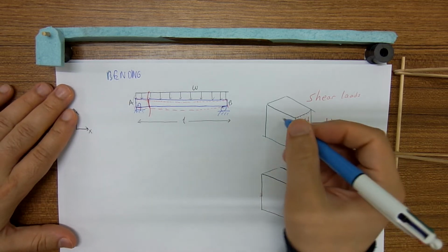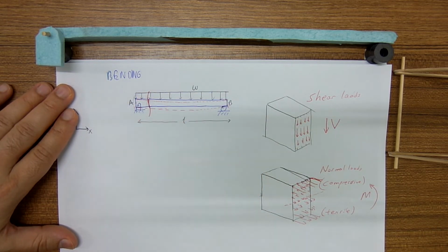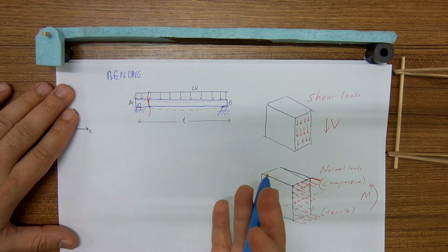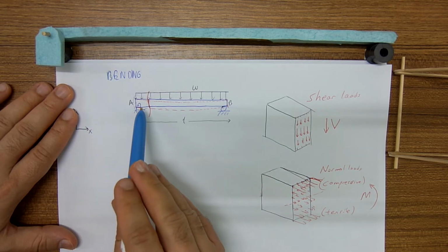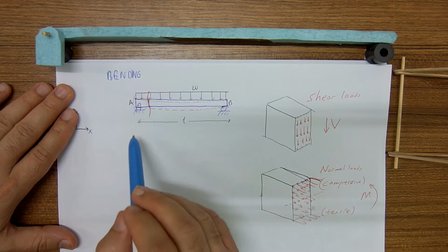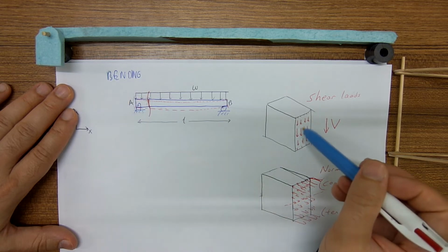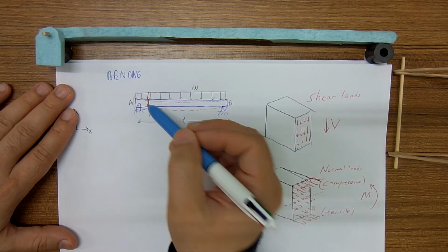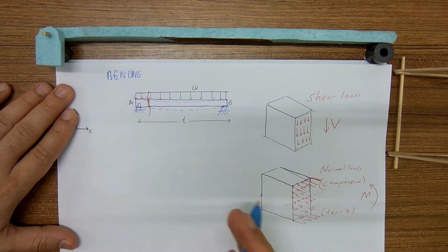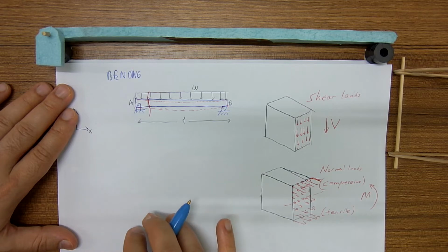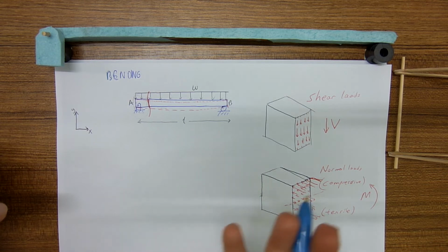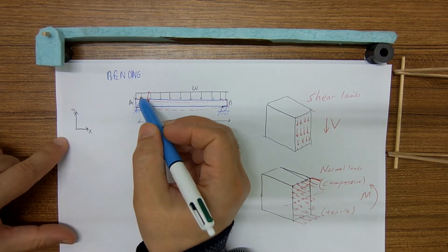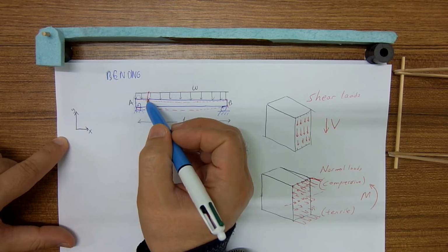If I draw a free body diagram of the segment 1, don't forget that the beam bending analysis of the beams is done on the left hand segment. So on the right surface of the left hand segment, the shear and moment values we see on the shear moment diagrams belong to the right hand surface of the left hand segment.